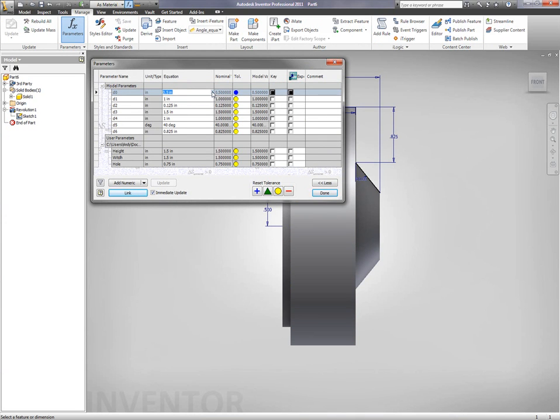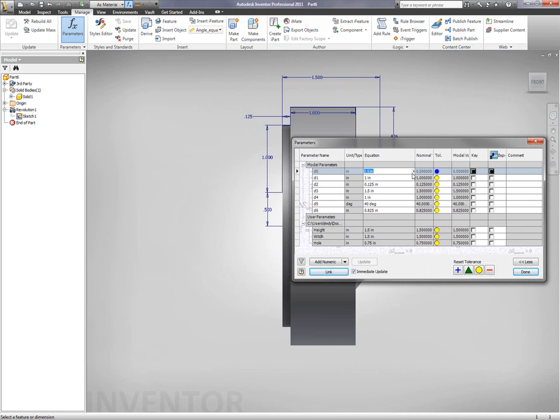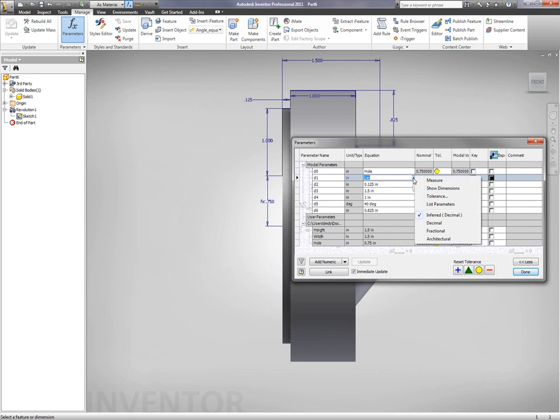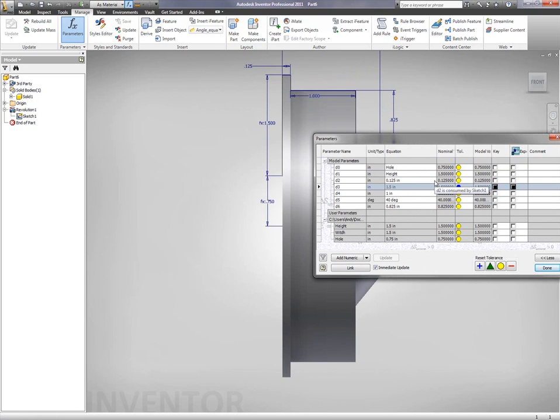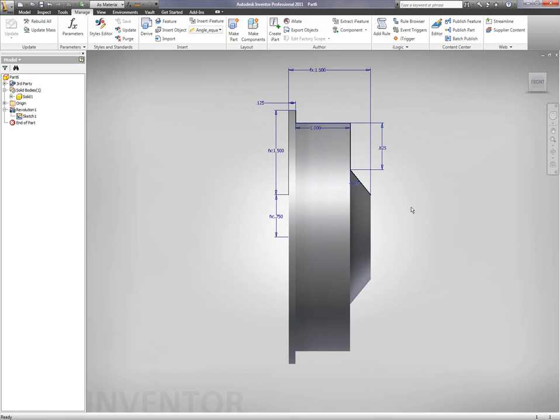It will automatically recognize the dimensions with the associated names, so we don't have to remember what D0 is and what D1 is, but rather we can remember the height, the width, and the hole diameter as the actual names that we put on the Excel spreadsheet, to simplify the changes that maybe are made by people other than engineers and things that way. So we'll go ahead and link up what D0, what D1, what D2 is to the associated dimensions on our Excel spreadsheet.